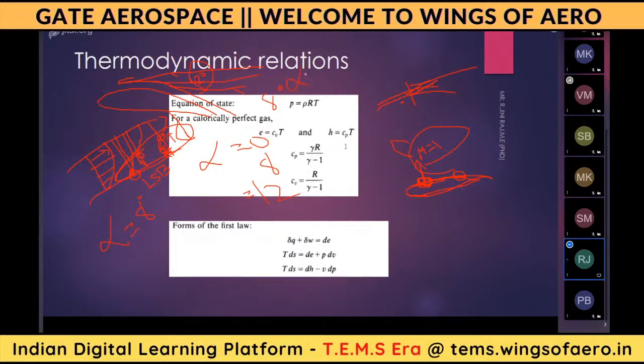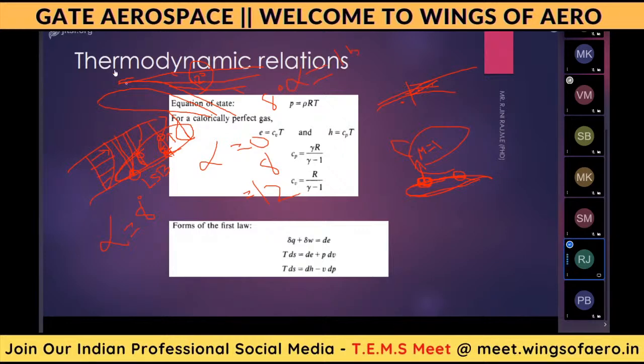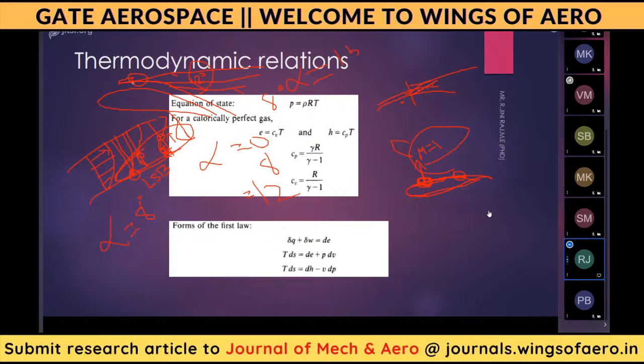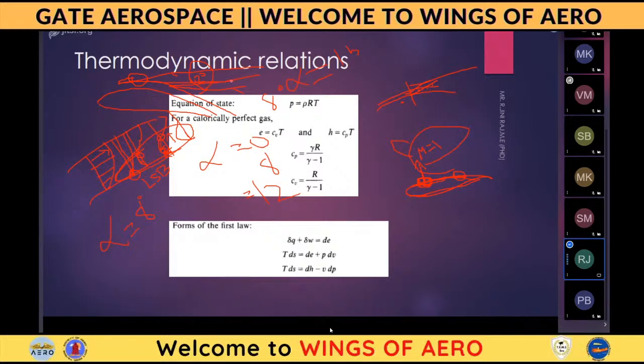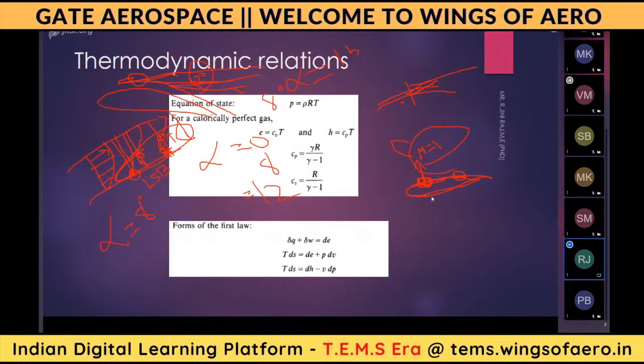That means when I increase the angle of attack to 15 degrees, I get the separation which I got in the NACA 4412 aerofoil. So there is a difference now. If the angle of attack is 12 degrees for a newly designed aerofoil, the separation is here. But for the NACA 4412 aerofoil, the separation is somewhat before.